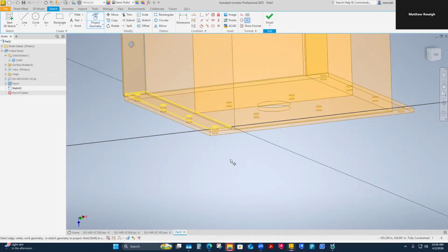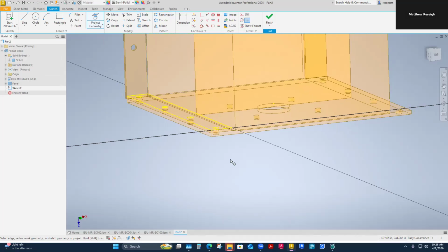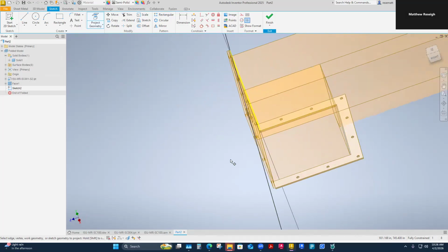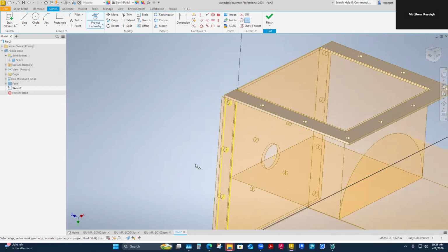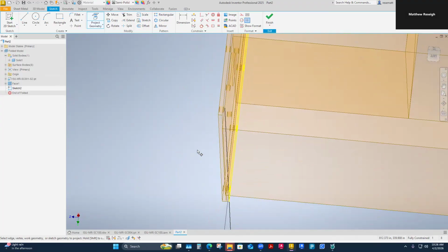If you had just welded on end plates, I really can't slip that auger through that little 2-inch hole potentially to even get it in. So my end plates are just removable. I can bring in my auger and then slap on the end plates and bolt them up. And that's what this particular part is doing: creating that mating flange for the end plate.